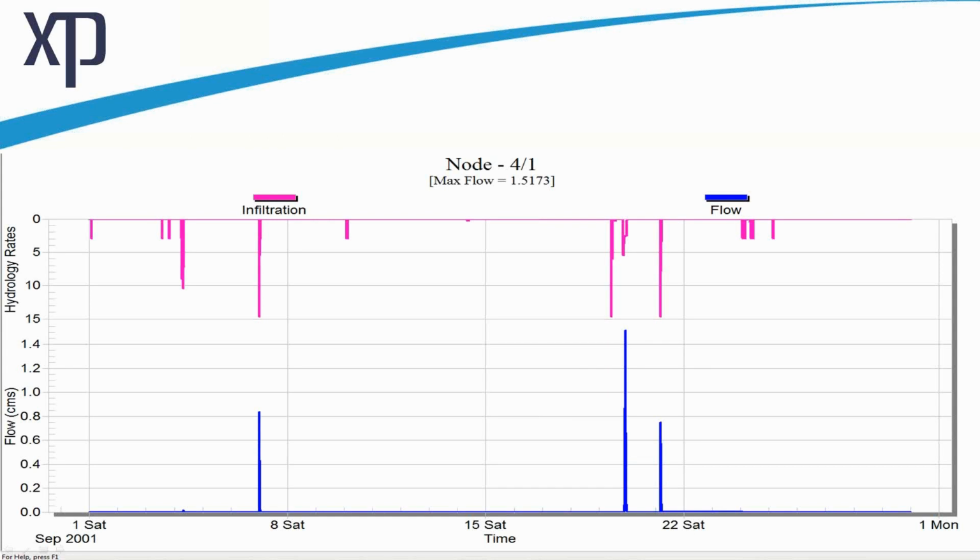This is just a simple graph which sort of showed how over a course of a rainfall event that infiltration can actually be quite a dominant parameter versus rainfall. So we've got flow as the blue line at the base, and you can quite easily see that we've actually lost these components of this particular catchment, which is a rural catchment, and we only have these tiny blips in runoff, I beg your pardon. But models can quite easily assess this. Again, it's getting the information to compare it against that makes this type of analysis difficult.